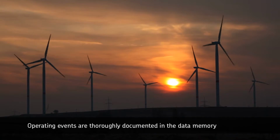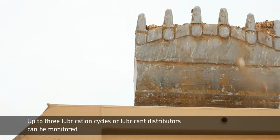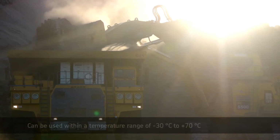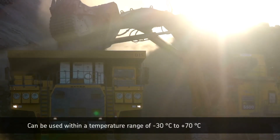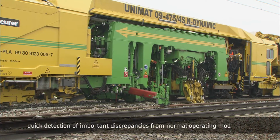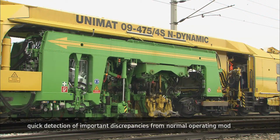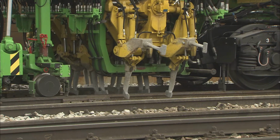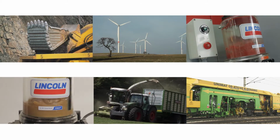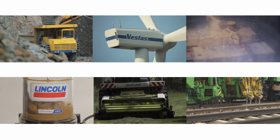Up to 3 lubrication cycles or lubricant distributors can be monitored using the pump P243 with integrated data memory. It can be used within a temperature range of -30 to +70 degrees. The remote monitoring of system status and simple operation of the operating system enables quick detection of important discrepancies from normal operating mode. That makes the P243 the ideal solution for industrial machines, agricultural and construction machines, rail work and tamping machines, and wind generators.